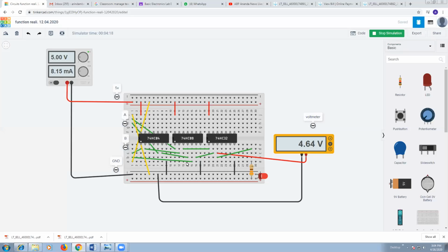Okay, got it everybody? As an input, and here pin number 5 is directly with the B bus bar, which is getting B. So then at pin number 6 we are getting A bar B. So A bar B is connected with pin number 2 of 7432.